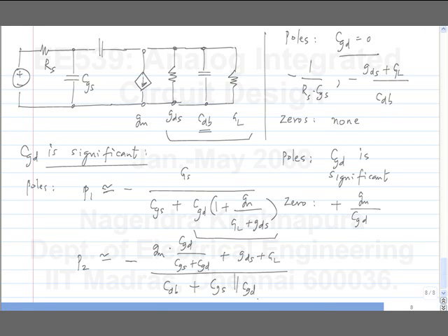So, we use different approximations for, let's say, small CGD and then large CGD, and the poles will go somewhere between one and the other depending on the value of the CGD. The approximation does help us study the circuit qualitatively, but whenever you make this approximation, you have to make sure that it was justified by looking at the answers. So, for instance, if P1 came out to be 1 megahertz and P2 is at 1.5 megahertz, then clearly the approximation was not valid. Any questions?